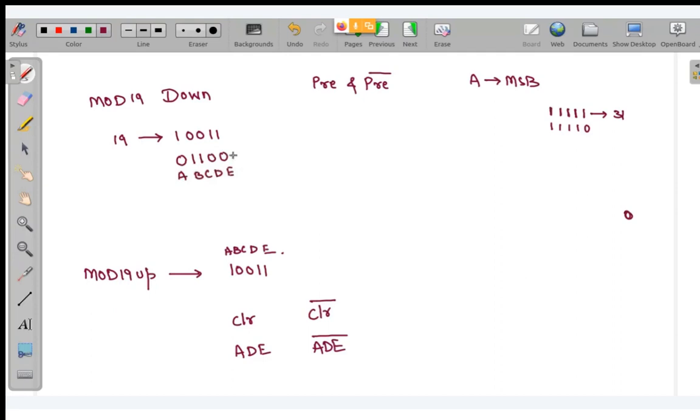I am sorry, I guess a few of you might have written it correctly. Now look over here. When I start counting from 1 1 1 1 1 and come to this state 0 1 1 0 0, this will be the invalid state. At this state I will be going back.